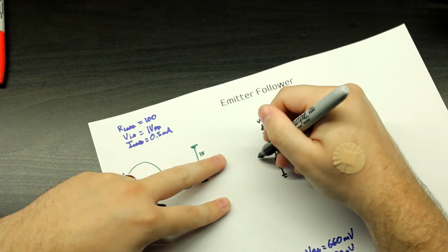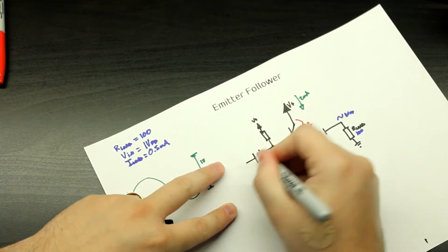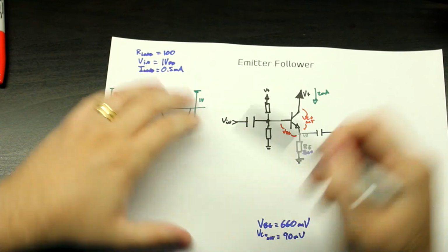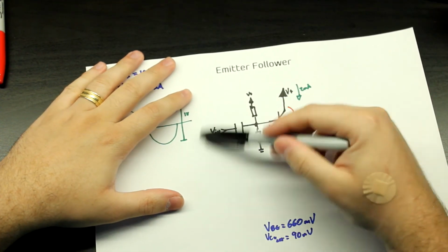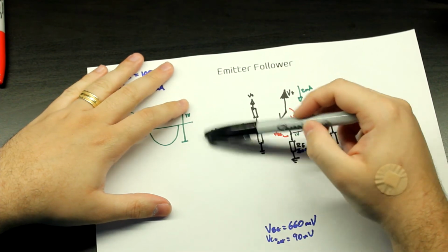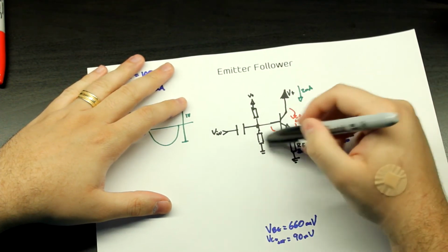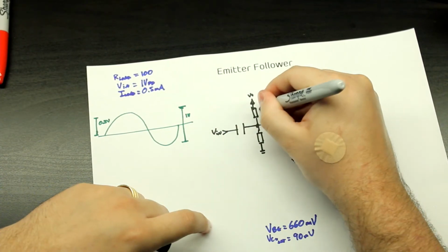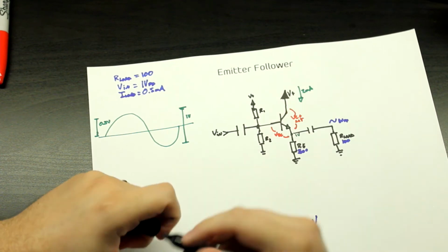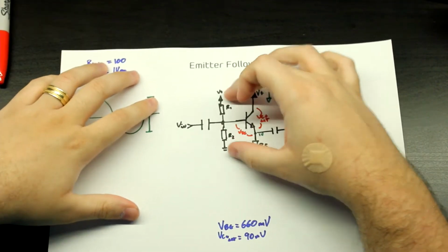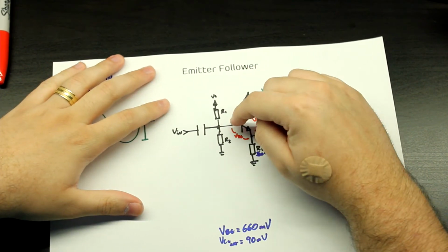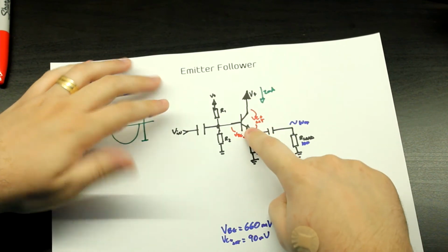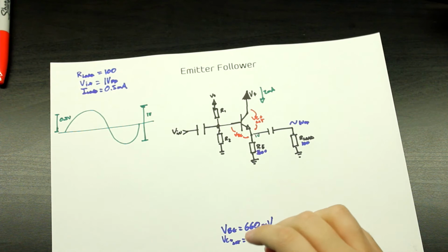Okay, and we decouple our input signal in here. We put this capacitor here just so that any DC that might be in this input signal doesn't upset the biasing that we've set for this device. So let's call this R1, R2. We need to make sure that this voltage divider can provide, first of all, the current required to keep this transistor on. That's very simple to calculate.